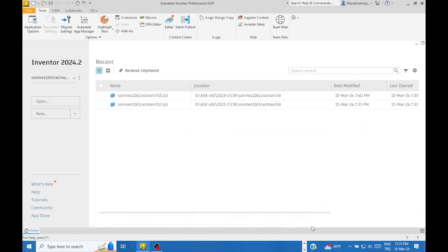And then, yes, you know the value of defining the work as a project. Define the work as a project. Okay, how? After opening Inventor, there is nothing yet. The first thing to pay attention to is that when you open Inventor, especially with administrator rights, you may find an active project. If there is an active project in the Inventor environment, then you cannot define a new project. Be aware, there is such a tricky detail.